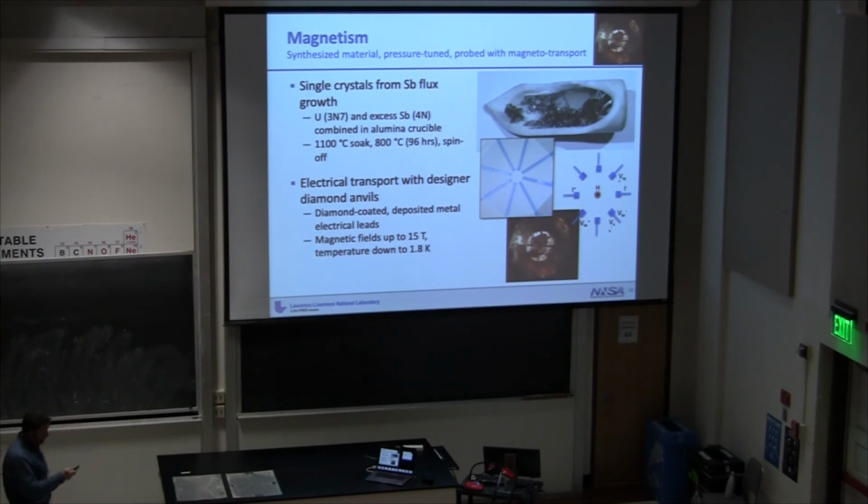We then come back and repolish everything so it looks like a diamond anvil instead of like a blob. And what happens is these microprobes get exposed only at the tips here. So all of this that you see here is kind of going down and away from you in the board. So it's going back into the board and it's underneath diamond. So if you were to come and touch that part there, all you touch is diamond. It's a flat surface of diamond. You can just see through it and see the microprobe beneath it. If you touch right at the tip where that line ends, that's exposed, and that's a piece of metal right at the tip of the diamond, right flush with the surface.